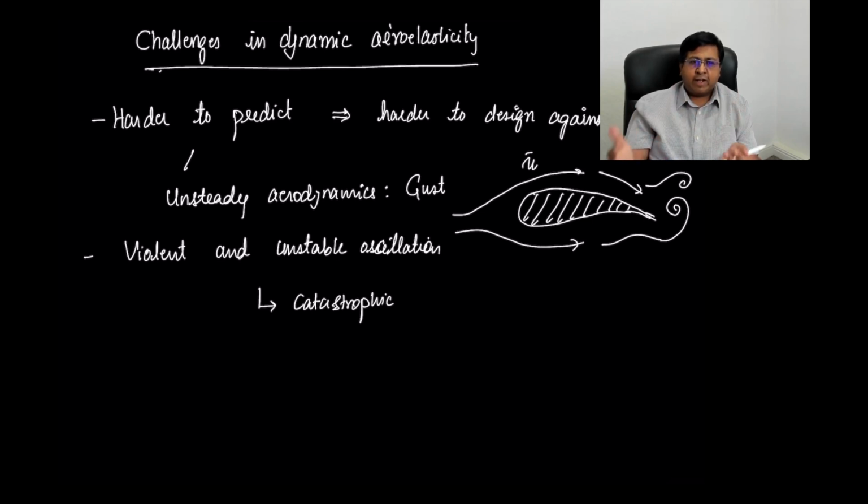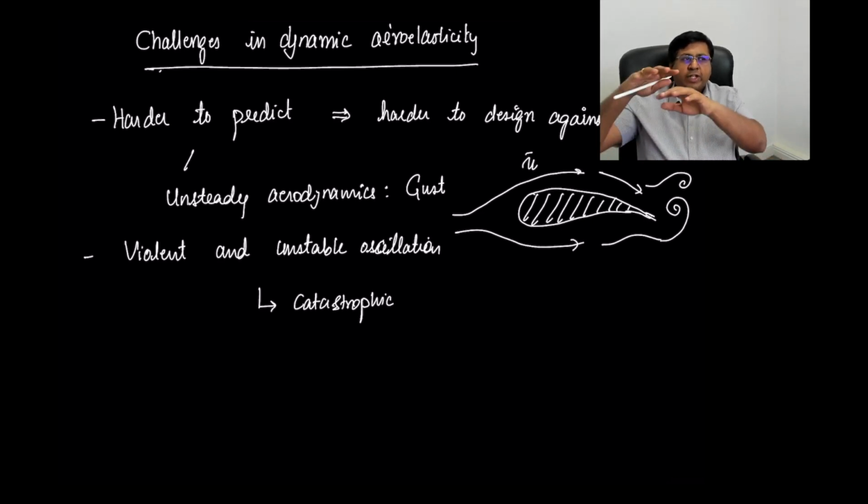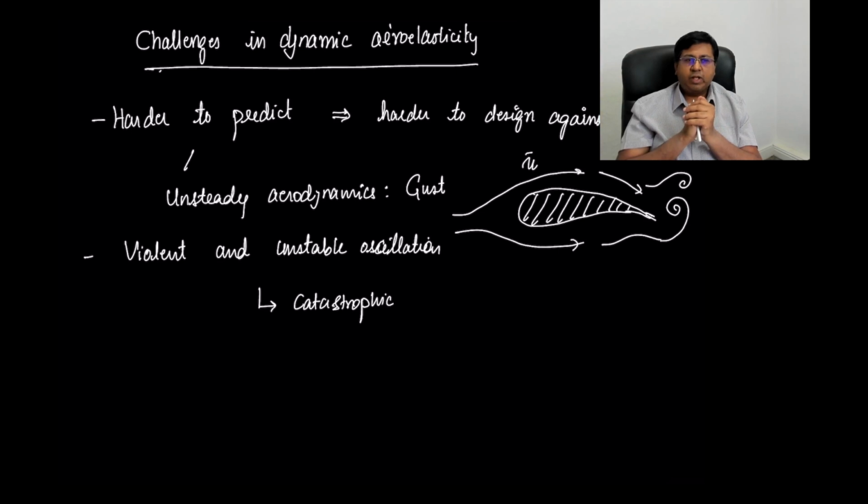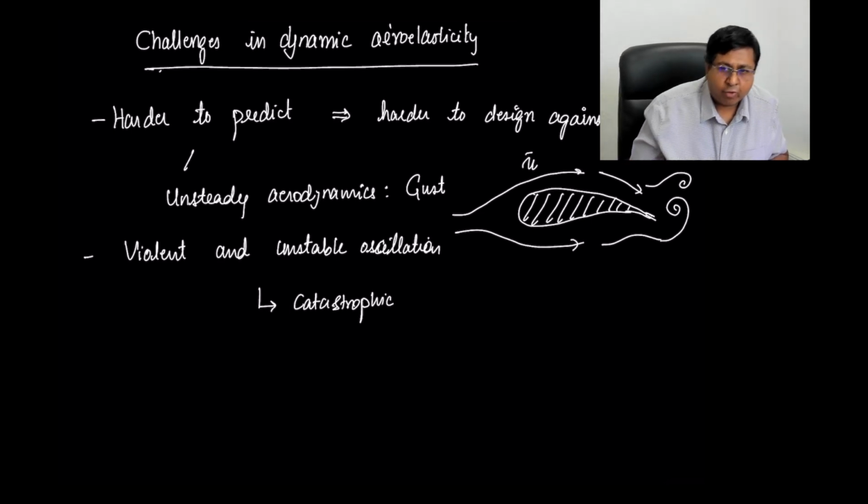Since the airfoil surfaces are affected, it in turn affects the flow surrounding the airfoil. So there's a loop here. The velocity is changing, which affects the airfoil structure or its dynamics, and because the structure is changing, that affects the flow velocity, and vice versa. So this is occurring over time rather than instantaneously. When we did our quasi-static aerodynamics, we assumed that the changes in the aerodynamics are instantaneous and the structures are rigid. But with unsteady aerodynamics, this changes. So there are various ways of accounting for this.